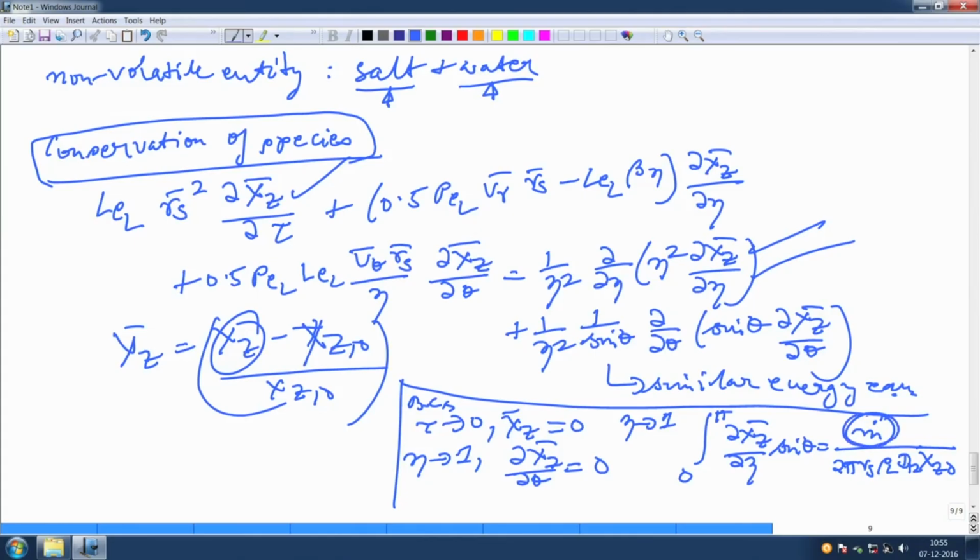Say for example, you have a kerosene droplet which has got dodecane, N-hexane, N-pentene, all these components inside. So, in order to study that, you have to study the individual volatility of each of the components. So, this m dot that you see over here will be the m dots of the individual components. So, it will be like m dot 1, m dot 2, m dot 3, m dot 4, right, and for each m dot you have to find out what is the corresponding Bm, Bt, etc.